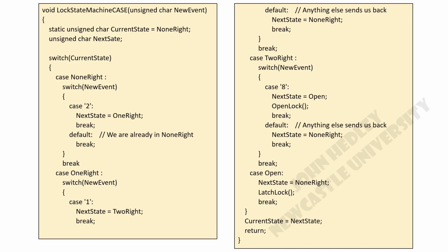There are two important points to note from this. Firstly, the control process was designed at the finite state diagram phase and not the coding phase. This has made it very clear for you to see what states and transitions are required, and it is much easier to program what you need. Secondly, the code for each case is very simple, albeit there are quite a few cases to consider. This makes writing and debugging the code much simpler, as you can easily check each small piece of coding for each case, rather than look through an entire, and possibly complex, complete program.